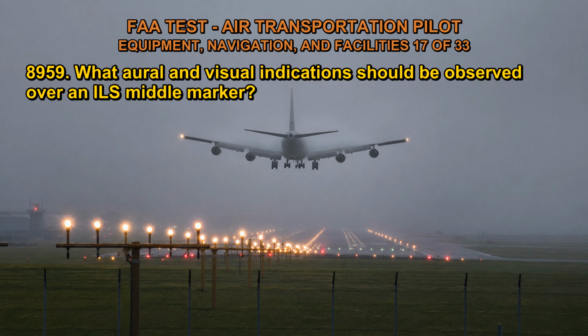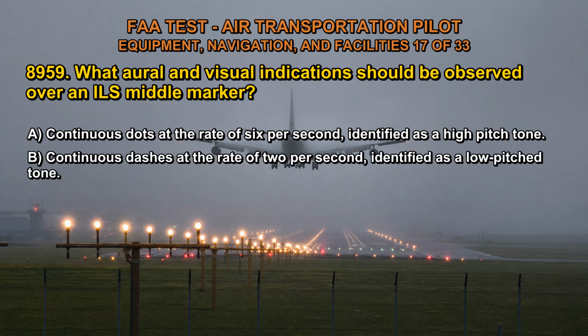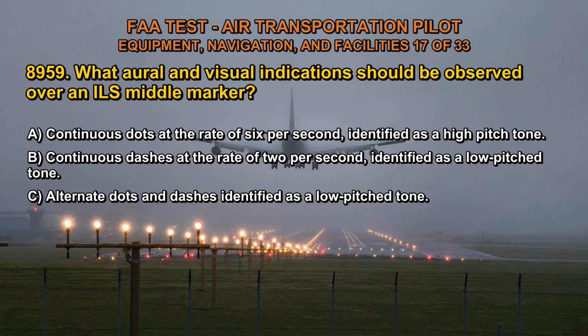8959. What oral and visual indications should be observed over an ILS middle marker? A. Continuous dots at the rate of 6 per second, identified as a high-pitched tone. B. Continuous dashes at the rate of 2 per second, identified as a low-pitched tone. C. Alternate dots and dashes identified as a low-pitched tone.